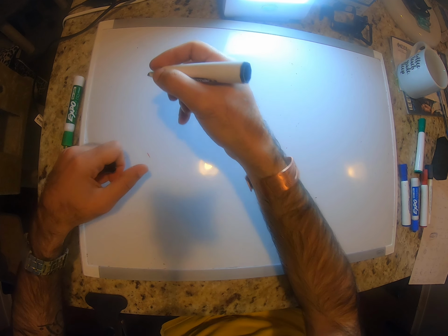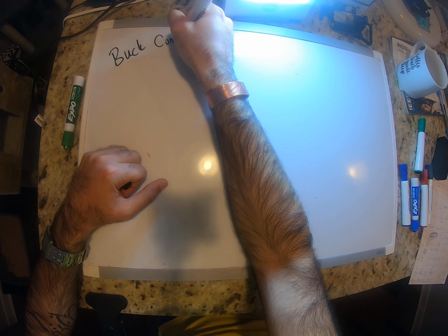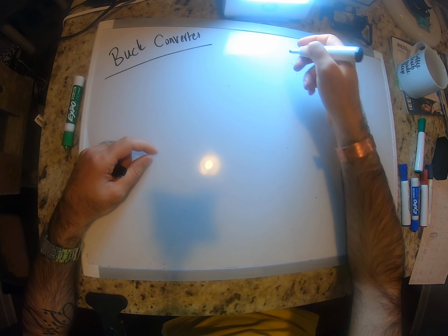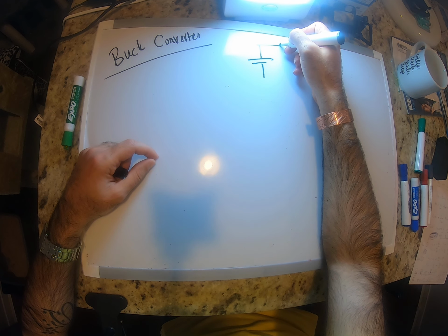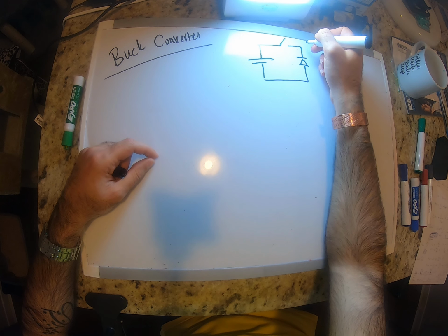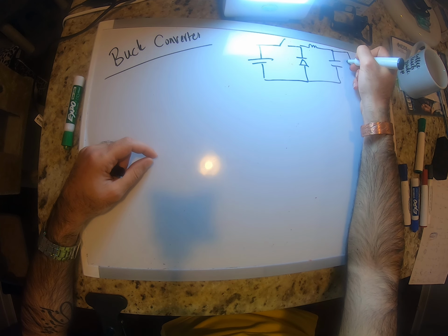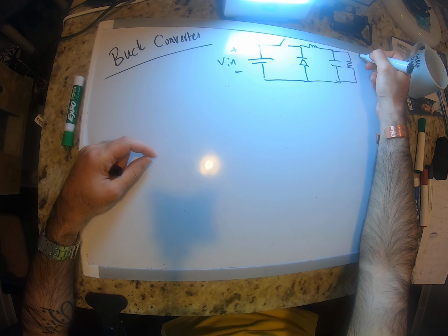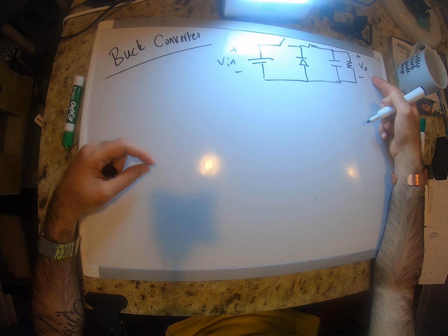So you guys saw the buck converter in this course and also in ELEX 3130. The buck converter is basically a step-down converter. It would have a switch, which can be a MOSFET or IGBT. It has a diode, an inductor, and a capacitor. And then we have a load here, right? So it would take a DC voltage and step it down to a lower output DC voltage.